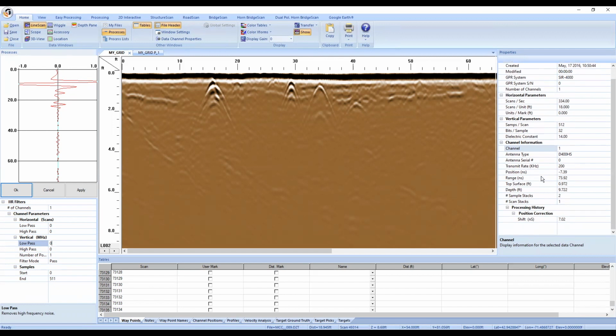The default high-pass, low-pass filters that we use set the low-pass at 1000 and the high-pass at 100. You can also do, usually I do 700 and 100 if I'm doing it myself, doubling the center frequency for the low-pass filter. And even though a quarter of 350 isn't 100, 100 is pretty close to the bottom edge of it. So that's a good number to use for your high-pass filter.